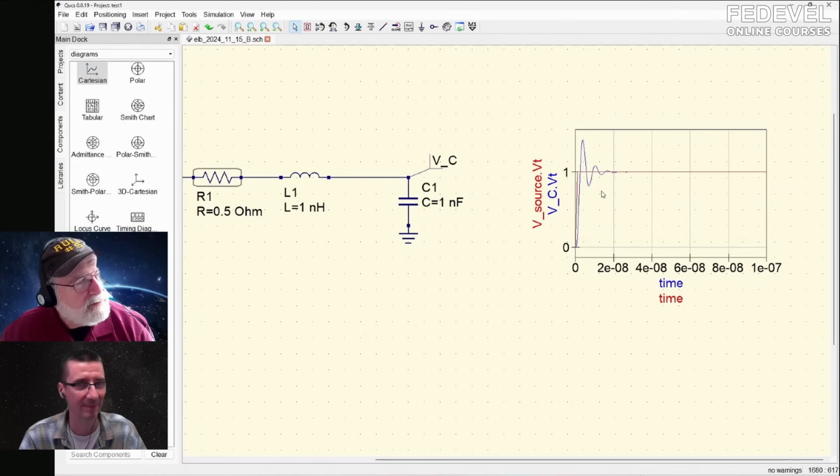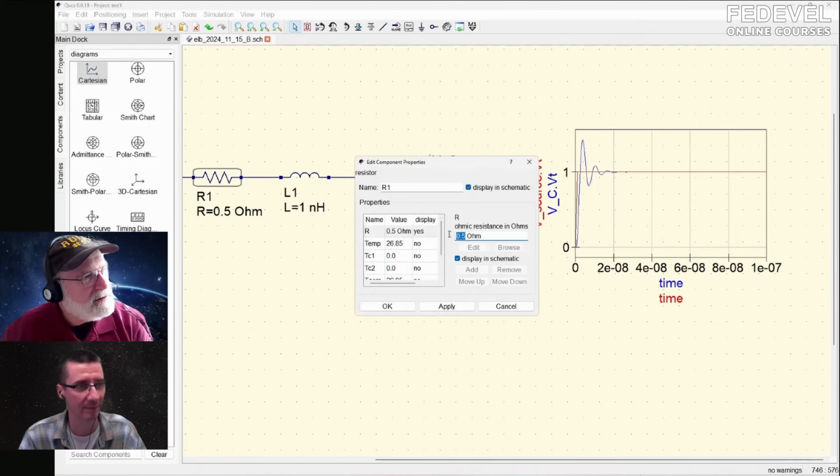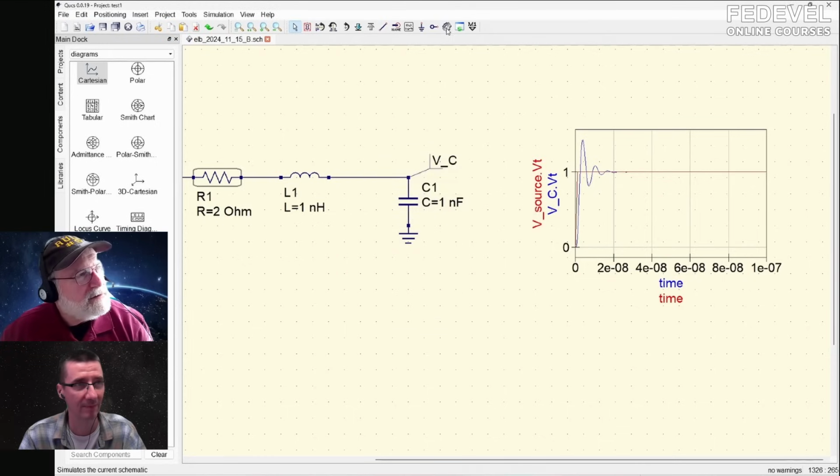And if we want it critically damped, so we had it underdamped, so it was ringing a lot. If we made the Q equal to a half, no, I always get confused, is it a half or 2? I'm sorry, I want it to be a half. That means critically damped. The impedance is 1 ohm, so I want the Q equal to 1/2, so I want 1 ohm over R to be a half, I want R to be 2. So let's make this 2 ohms,